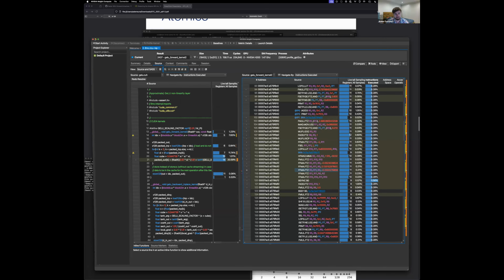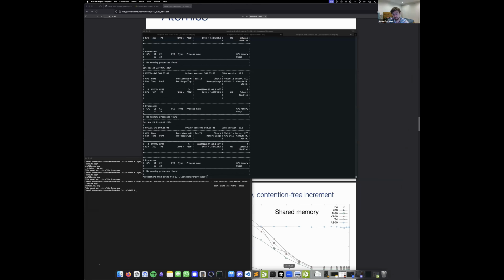There's both the command line option and, in Nsight Compute, clock control here. We can do base and none. None means the clock is dynamic and dependent on thermals and other things. But yeah, you cannot measure power in Nsight Compute. And even if you could, you wouldn't want to, because the way the profiling works changes the workload completely. You want to use nvidia-smi or other APIs to get that.